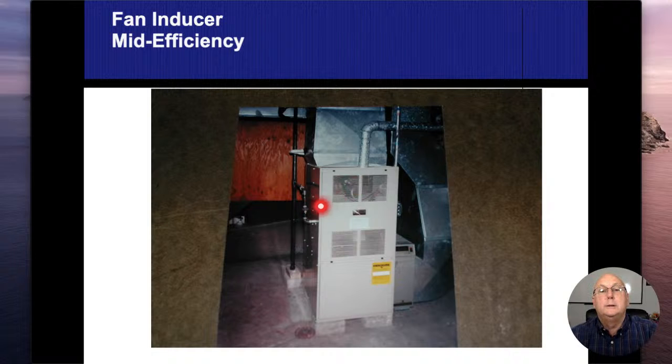And one of the questions I get is, when they talk about the vents and the vent connectors, sometimes they're metal, sometimes they're PVC. How do I know when it's a high efficiency? What are my clues? How do I know it needs to be plastic, or how do I know it needs to be metal? And we cannot mix the two of them, all right? Everything goes to the housing, and I'll show you a closer up picture of it in a little bit. But everything goes to the housing of the inducer fan.